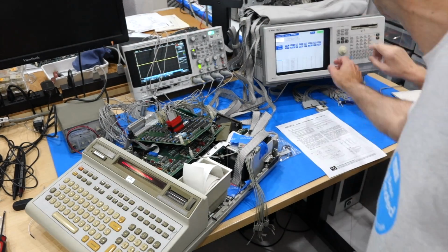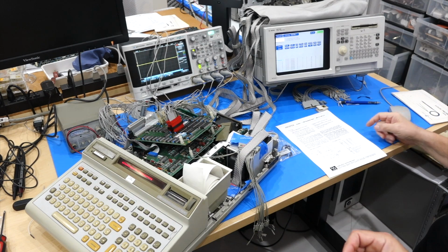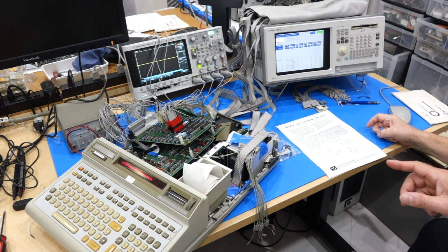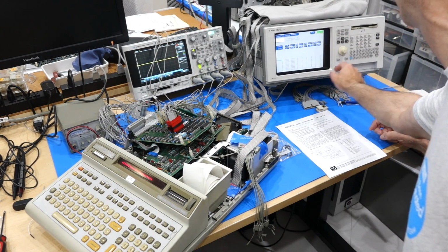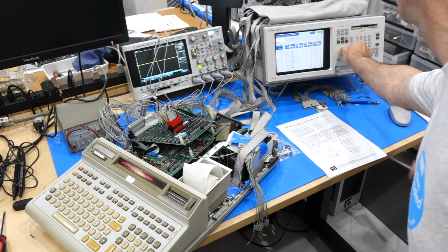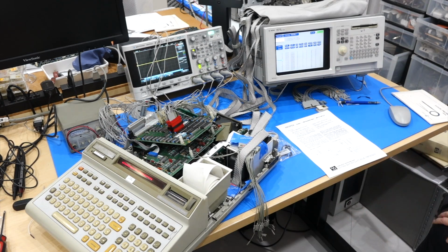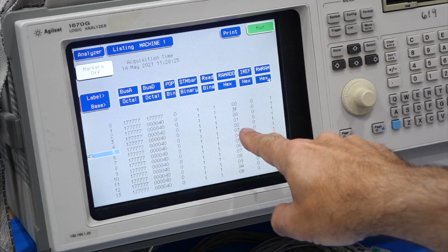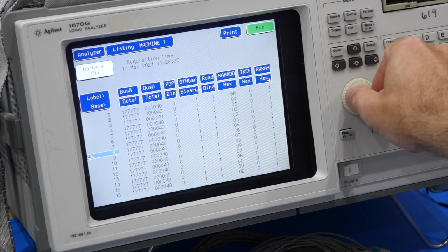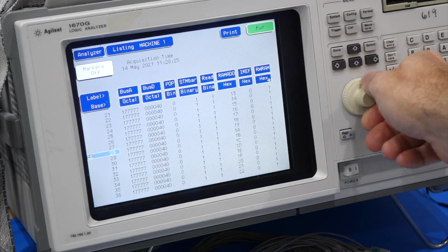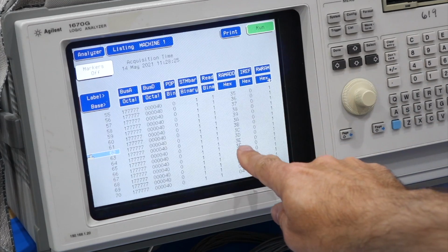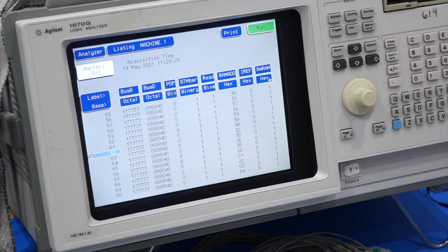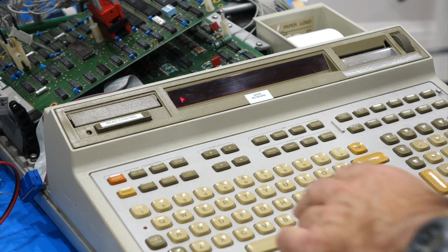Okay. So you should see, if I set that one up correctly, you should be able to scroll down and see refresh RAM address. Yeah, I see it. 1, 2, 3, 4, 5, 6. It's refreshing. You see it here? Yeah. Okay, so I see the refresh. It counts 0, 1, 2, 3, 4, 5, 6, 7, 8, 9, A, B, C, D, E, F. So that's what we were missing. The Intel chip wasn't just sending the addresses, and now it sends the counter, goes to 3F, goes back down. So it seems to be back.